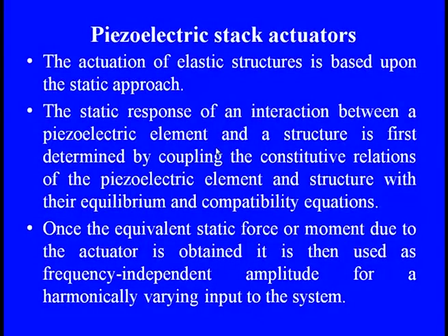We need to check it out. The two things are the equilibrium part, the stable feature, and second the compatibility part, and based on these we can frame the equations in either the mechanical strain or the electrical displacement. And once the equivalent static force or moment due to the actuator is obtained, we can use the frequency-independent amplitude for harmonically varying input of the system. So, this is one way the piezoelectric stack actuator can be used.